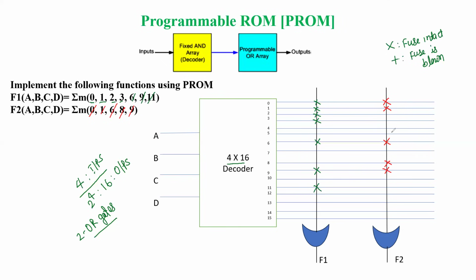So now we have function f1 and function f2 represented here with the help of decoders. If we are interested, we can simplify this again later with the help of an AND gate, or here we can go for the K-map also. After getting the K-map, later we are going to discuss it. So again, we'll obtain the Boolean function with the help of the K-map. On the basis of that, again, we can see the combination of the decoder output also.